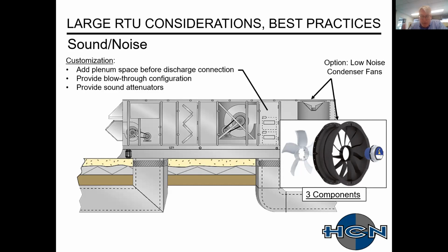It ends up pre-swirling the air, and then it also directs the noise upward instead of horizontally. And then the last component in the blue there is your EC motor. These 3 components end up providing more CFM at a lower RPM, and that translates into quieter operation, as well as making it more efficient.